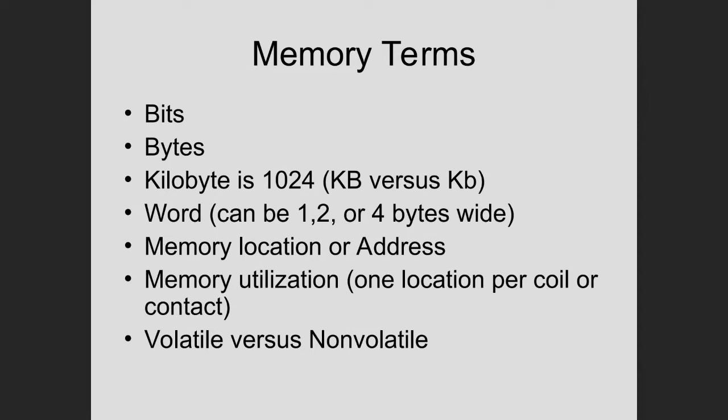Now, earlier we talked about the differences and the similarities between PLCs and PCs. And pretty much they're the same device. A PLC is a computer. But there are some differences, and here's one. I want to point out one big difference between a PC and a PLC. PCs, and this includes your cell phone, microprocessors, everything else except for a PLC, are byte-oriented devices. A PLC is a bit-oriented device.